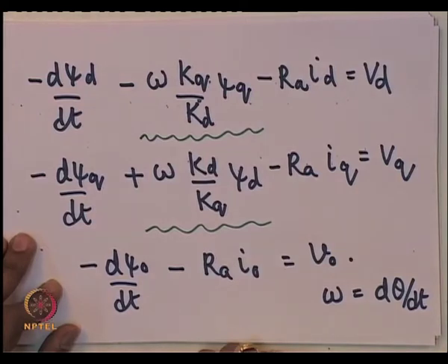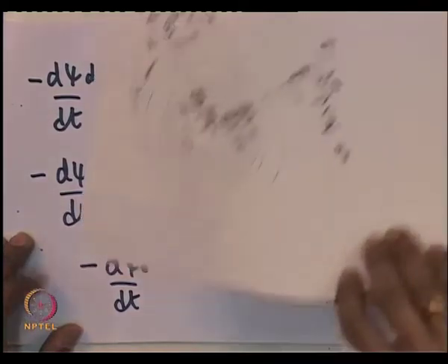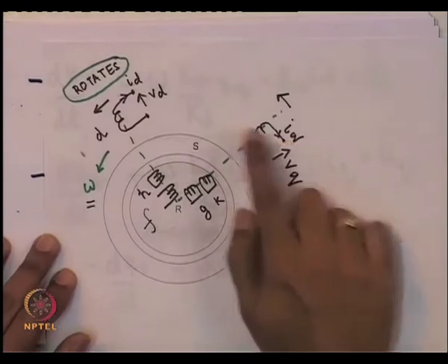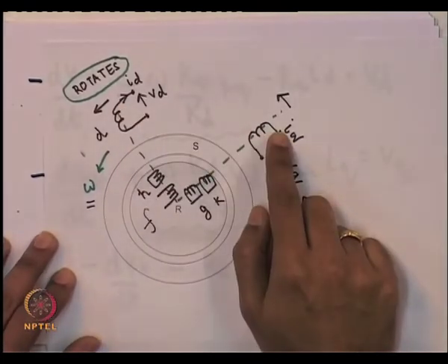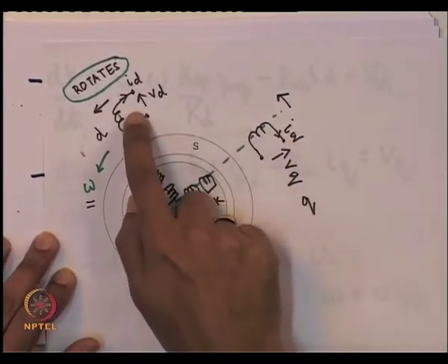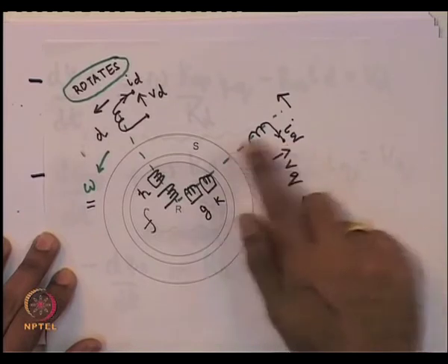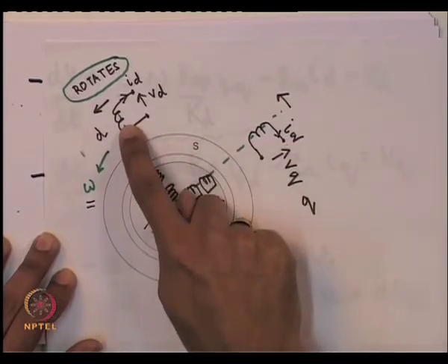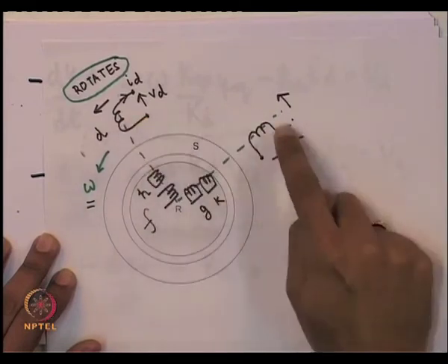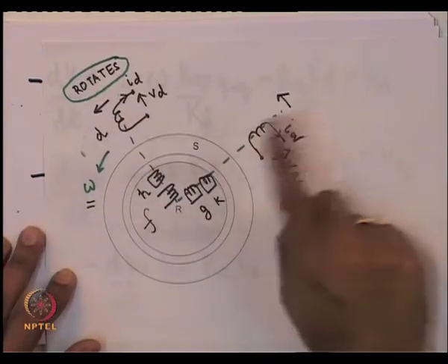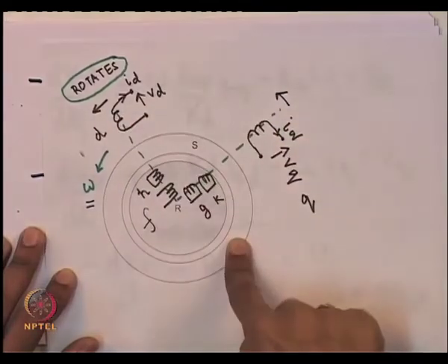Okay. So, although sometimes it is tempting to start from a kind of physical model of rotating windings, when we come to obtaining the flux equations in the D coil or the Q coil, remember that there are speed EMFs in the D coil due to the flux in the Q axis. This cannot be explained by just starting off from this model.